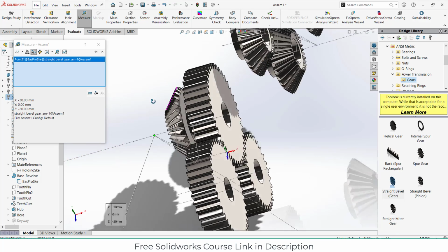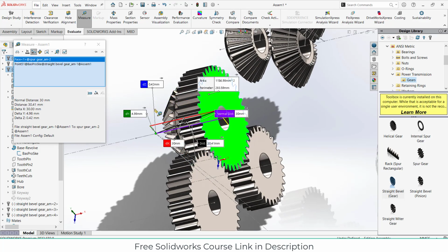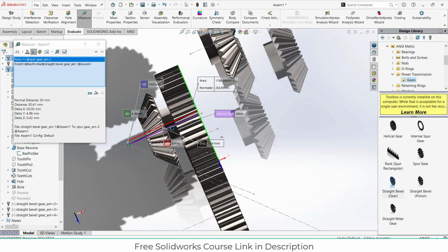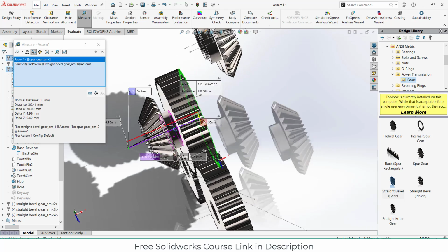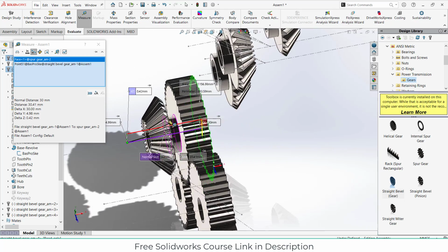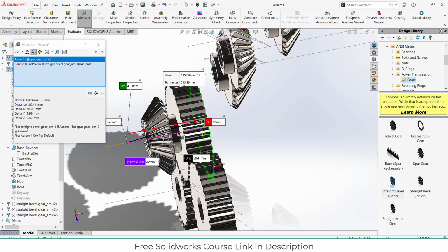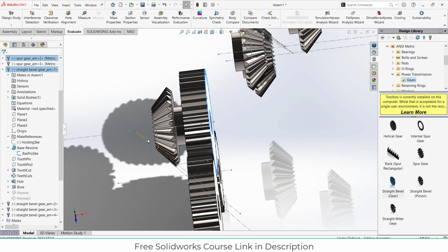Again, I'm saying that I don't have any dimensions or clue. I'm just making it for my imagination. So don't ask me where the drawing is, etc. So it's 30 mm, as you can see, this purple line, 30 mm. So I need to create a plane 30 mm from here.